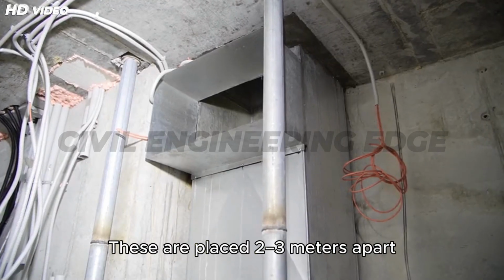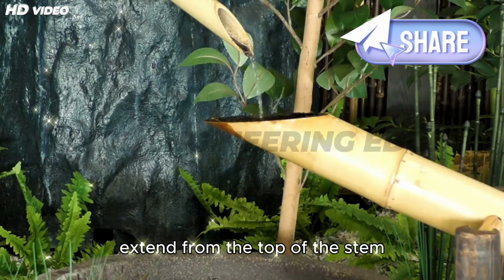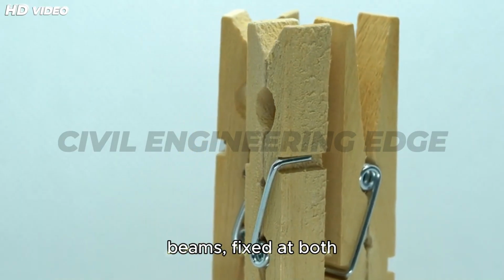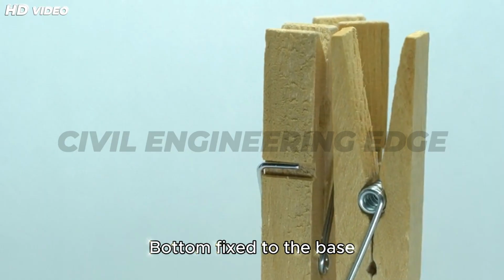These are placed 2 to 3 meters apart along the back of the wall and extend from the top of the stem to the end of the heel. They are designed as triangular vertical beams, fixed at both ends. Top fixed to the stem, bottom fixed to the base slab.